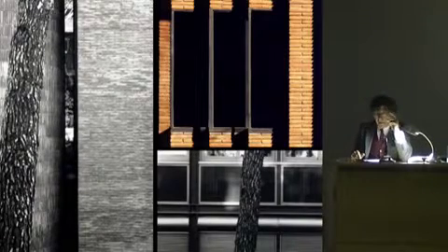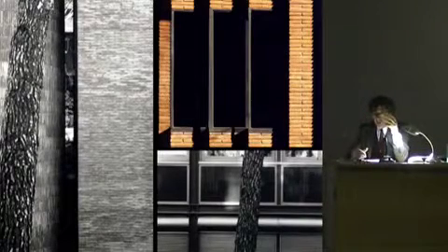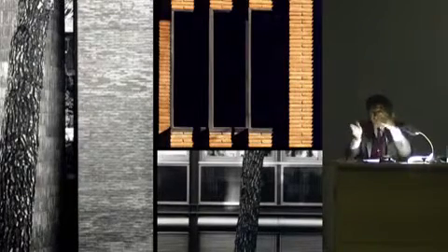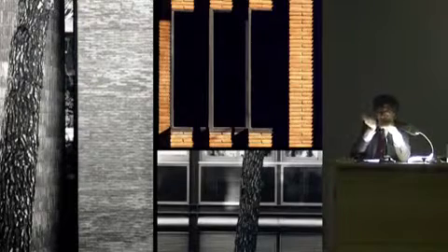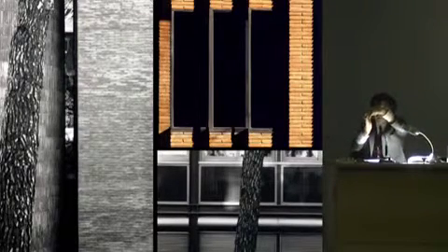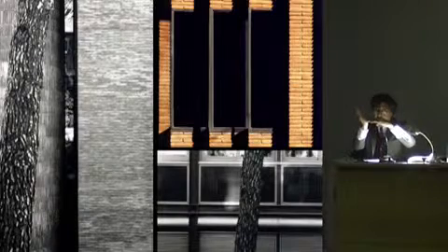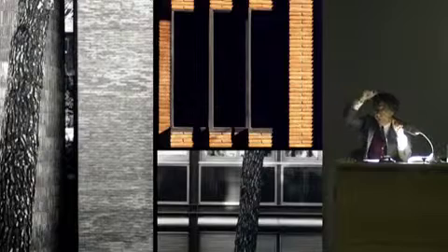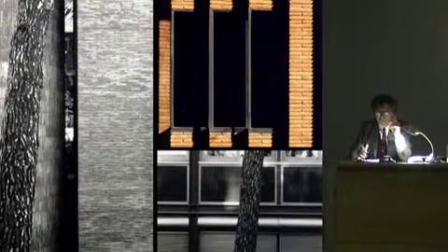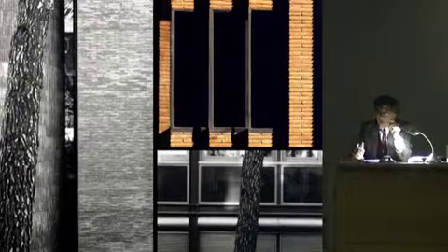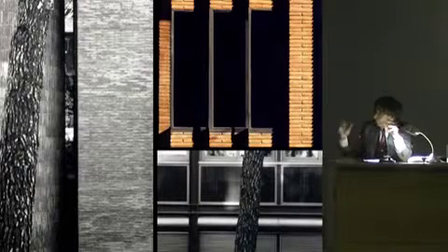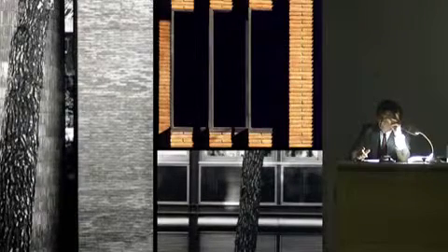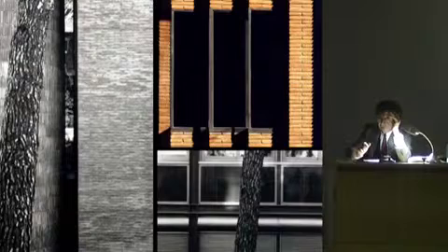Oh, here in this color picture you see this sort of tooth wall, and there they had to build a tilted wall on a building that's lined with brickwork, so that it would imply cutting the very first brick and the last one due to the inclination. So to prevent this, they create this serrate effect on the wall, so no brick needs to be cut. You may think that's a bit exaggerated. Yes, but this wall is facing west, so they're working with the shades, and it's a wall that becomes part of a facade, like a frontal piece.